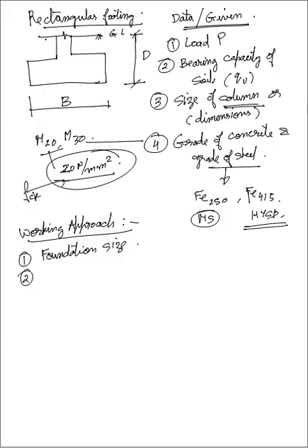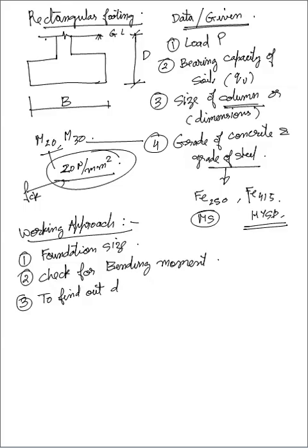First is foundation size, second is check for bending moment, third is to find out the depth required. It is very, very important.